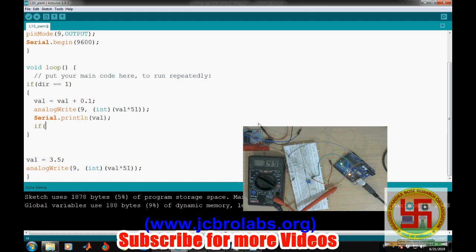Okay, so we can do that, because we don't want it to go to 5.1, otherwise we'll get a kind of jerk on the signal. So you can try it. So we'll do val plus 0.5 is greater than 5, so we are checking for the one step ahead. Then we will change the direction equals to 0, right, and then we'll provide a delay of, let's say, 250 millisecond, so that it is increasing smoothly.